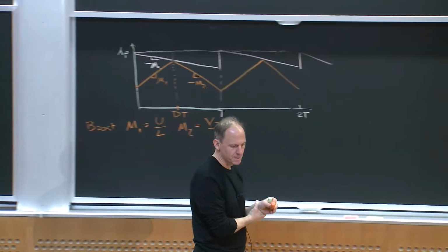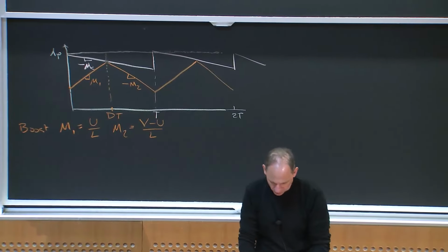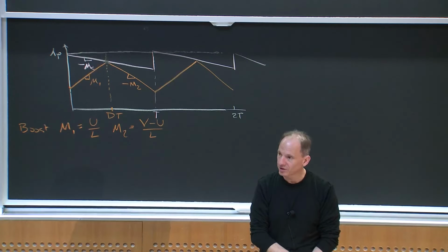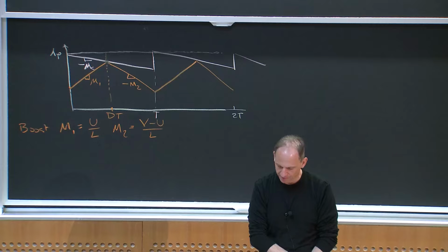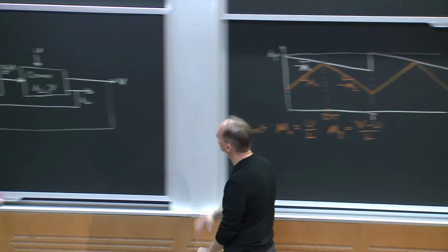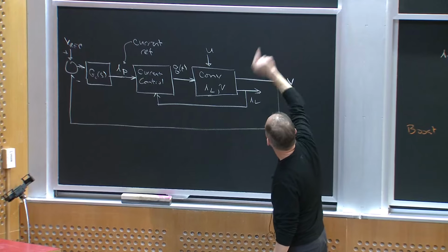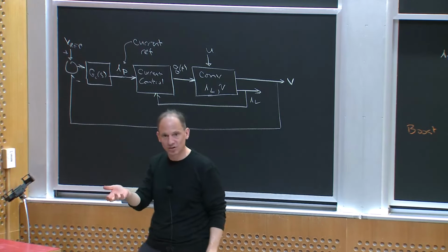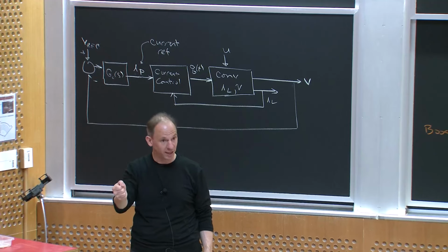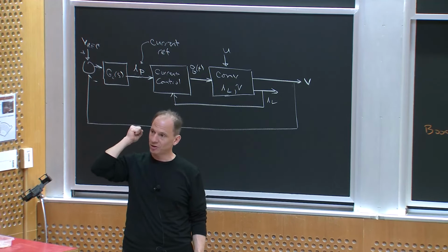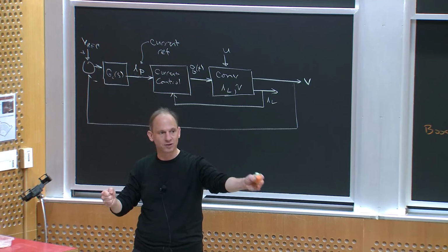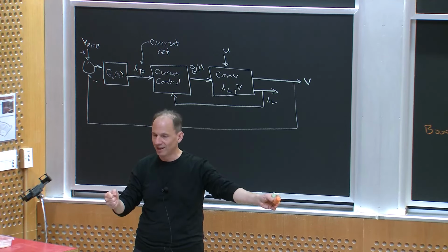Okay. All right, so one thing it gives us is this cycle-by-cycle current limiting. The other thing it's going to give us is better dynamics, okay? The question is, how do we analyze the dynamics of this thing? What did I do before? The thing I did before was we averaged the circuit, either the circuit or the state space model, and came up with a duty ratio, and then we linearized it, and we came up with a conversion between the duty ratio and the local average inductor current and local average output voltage, right?